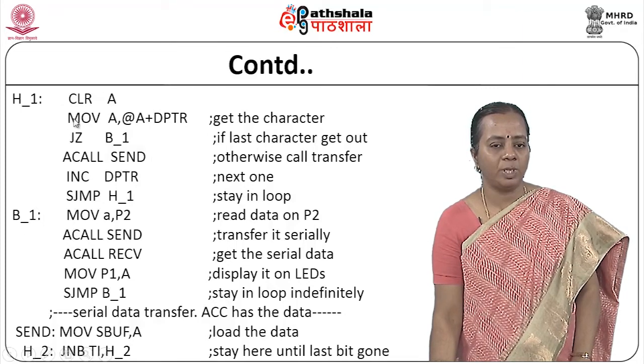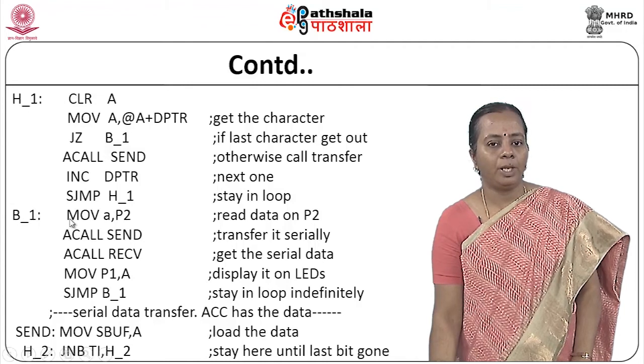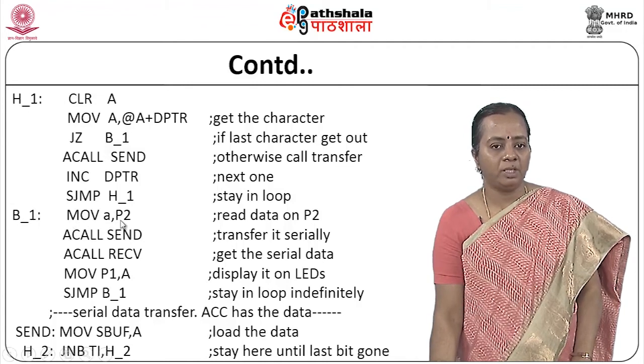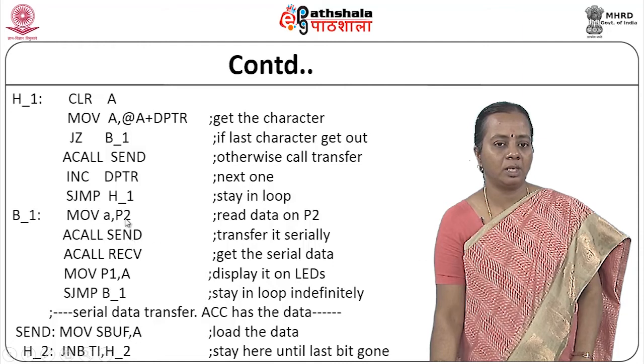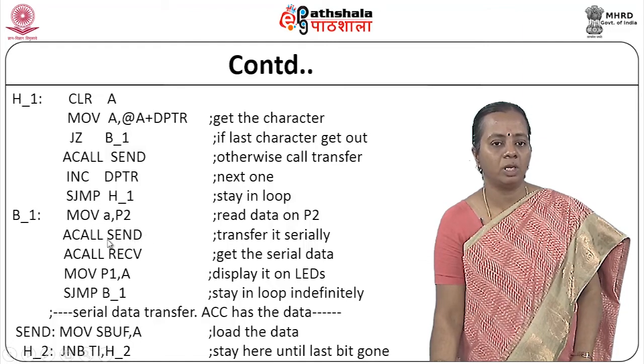So this has been done only once. Now when you are looking at here, I have read the data from P2, MOV A, P2. P2 content is moved to A. Now I am sending it again, using a CALL SEND. Send is a serial communication transmission routine.